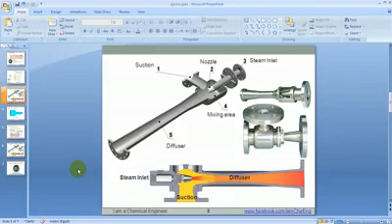The second one, and the most important one, is that air with a mixture like hydrocarbon in here would result in a fire hazard, since you would be completing the fire triangle, which is air, hydrocarbon or any combustible matter, plus ignition, which may be self-ignition here. You can expect self-ignition or anything else, so this is not a good thing to do in your refinery.